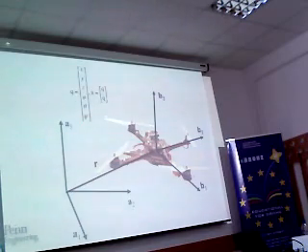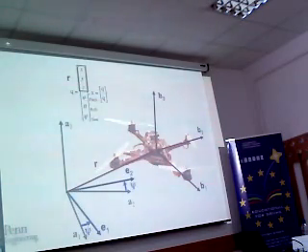The position vector of the center of mass, and the roll, pitch, and yaw angles tell you what the orientation is. The state, of course, is composed of configuration, a six-dimensional vector, and its rate of change, in other words, the velocity. The roll, pitch, and yaw angles follow our usual convention.